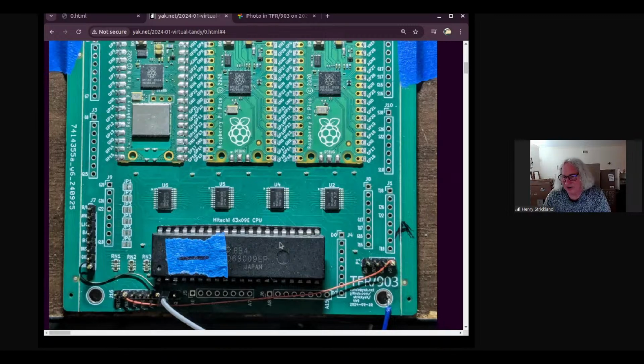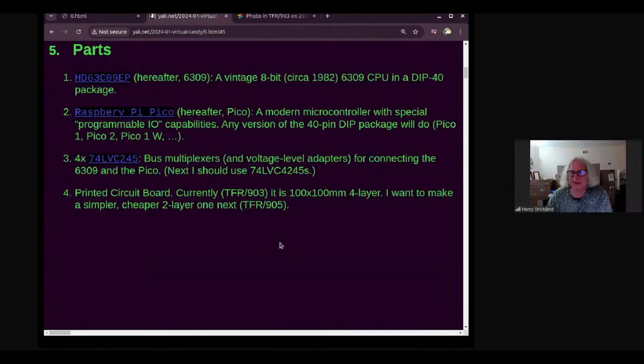The blue wire is a ground that I had soldered into that ring, and the white is an oscilloscope probe. But the green wire and the orange wire, those are covering up for mistakes. I actually made my pull-ups pull-downs and my pull-downs pull-ups. Not a huge mistake, but 2 wires had to get added.